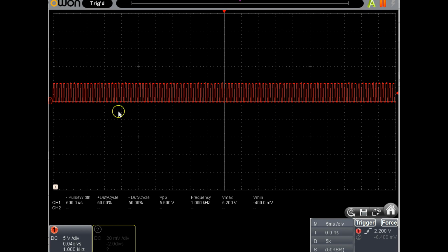The sampling rate of this oscilloscope is 2048 samples across the entire screen, and so the sample time at this particular time base is going to be 100 milliseconds divided by 2048. The sampling frequency will be 1 over that, or 2048 divided by 0.1 seconds.